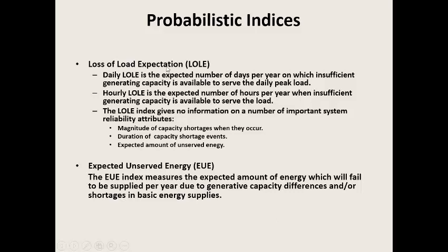One of the very commonly used probabilistic indices is the loss of load expectation. The loss of load expectation has been defined in two ways. One is what we call the daily loss of load expectation. So this is the expected number of days per year on which insufficient generating capacity is available to serve the daily peak load.